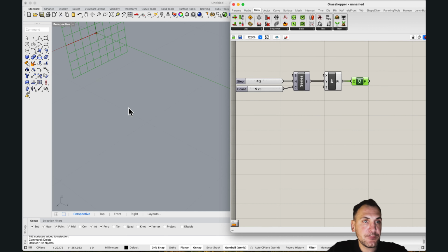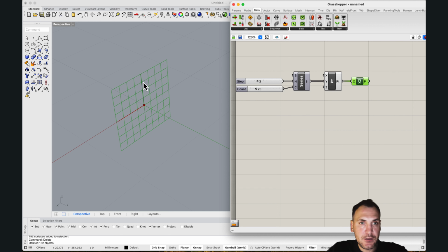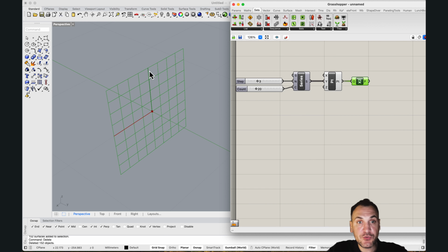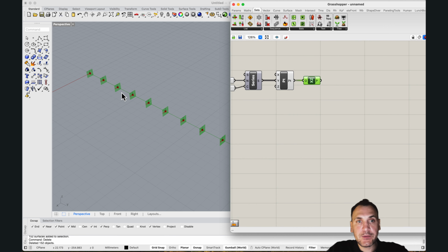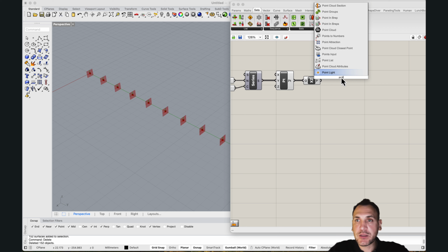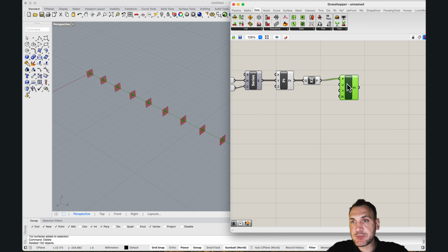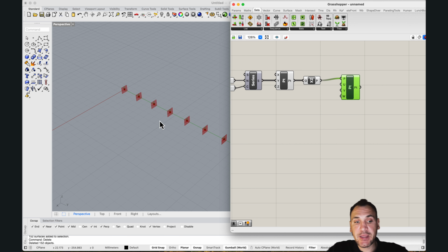And if you zoom in, you can see these are basically the plane orientations, and we have new coordinate systems along these points, right? So my X is pointing in this direction, Y is pointing upward. And if you want to create any point in relationship to these, you can use point oriented and then use these planes. And now those coordinate systems actually come in handy.